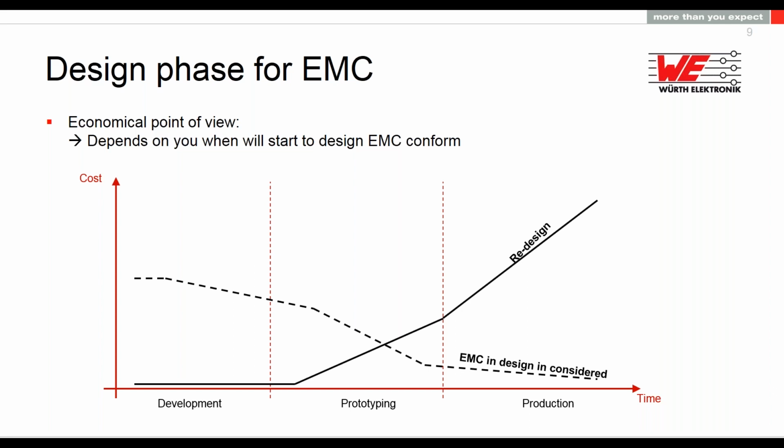Do I need to make here a very simple LC filter, or is it not my problem, and the guy from the EMC lab must solve that problem? Well, if you do it like that, it's difficult. I would suggest using a pad for a capacitor on your PCB where you know that you have a high frequency issue.